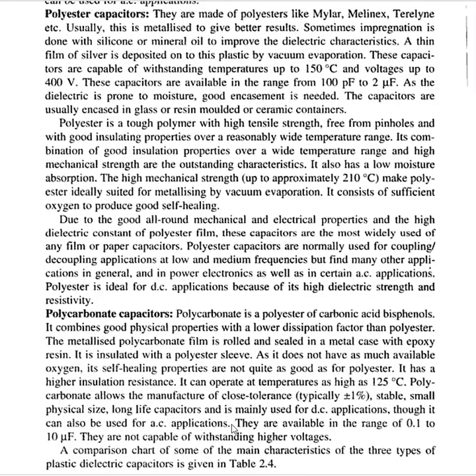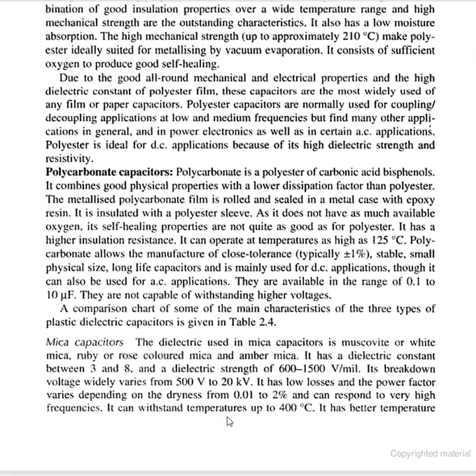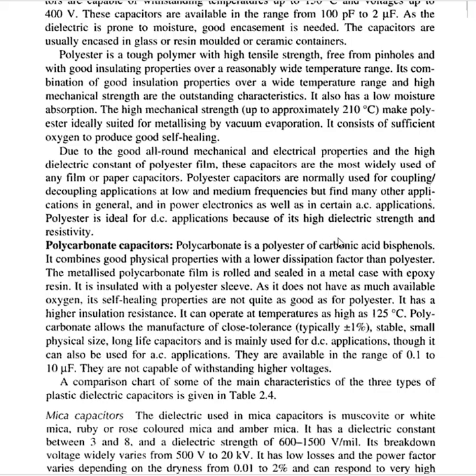Polycarbonate capacitors. Polycarbonate is a polyester of carbonic acid bisphenol. It combines good physical properties with lower dissipation factor than polyester. The metallized polycarbonate film is rolled and sealed in a metal case with epoxy resin.